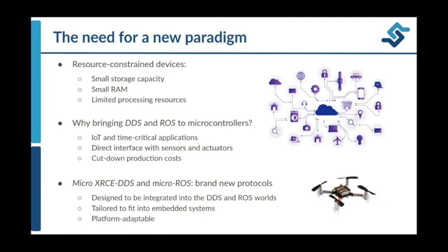So in this presentation, we will see how these protocols combine these key features. So be lighter in the first place, but also be easily integrated in the DDS and ROS world. Okay, the idea basically is isolating a simpler part of the library that takes care of the microcontroller side from a more complex entity that runs instead on a more powerful machine and is in charge, this entity, of bridging the low resource device with the fully deployed DDS and ROS worlds.